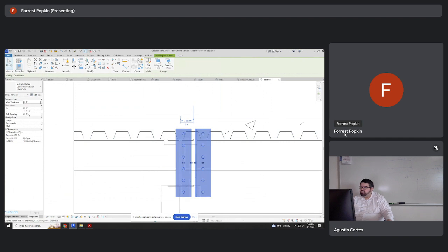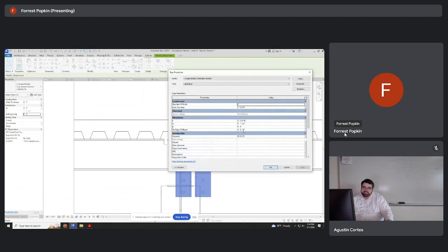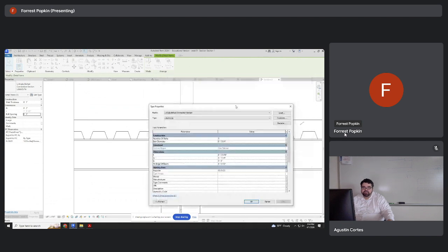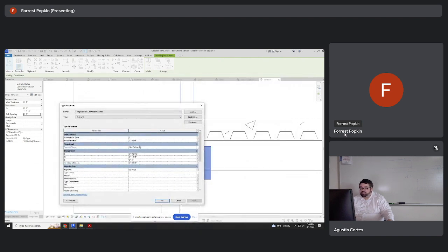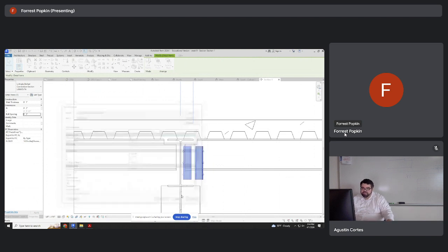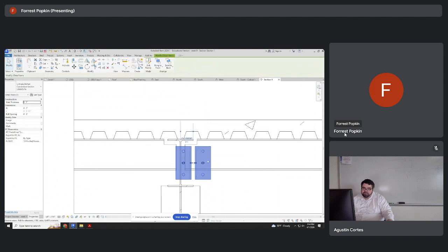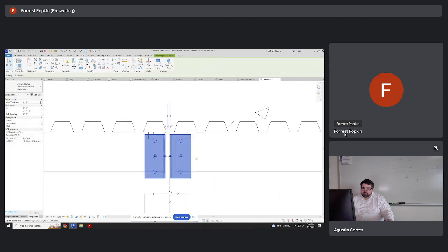So here, you realize it's parametric, and it says what's the height, what's the bolt spacing. I'm able to modify these things. So number of bolts, I can make it say just 3, and it will change it and make it a little bit smaller. Then it'll say what's the diameter of my bolts, and again, these are all something that somebody somewhere has to figure out for you. So you don't want to just, in the real world, toggle with these things and it not matter. But eventually you can place them.